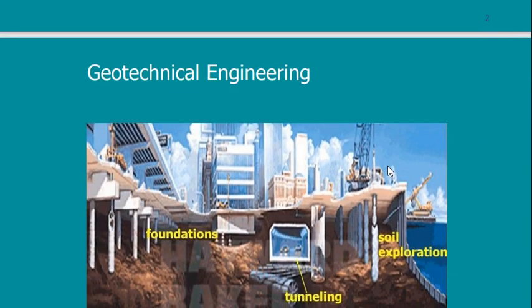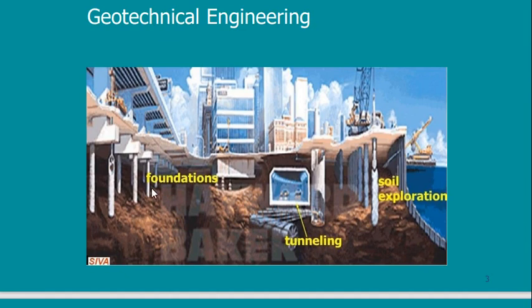This is what we usually see. But what we did not see is the full picture. What is the full picture? This bridge has, below ground, something called foundations. You maybe heard about piles, shallow foundations, deep foundations, but there are lots of types of foundations. Do all bridges have the same type of foundations? No, each bridge has its own type of foundation. How can we choose this type? Which is better for this type of bridge? It really does not depend only on the type of the bridge, it depends also on the type of the soil. So I need to know what is the soil beneath so that I can design an adequate type of foundation.